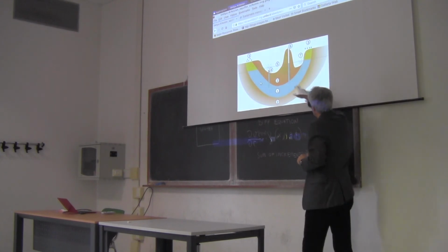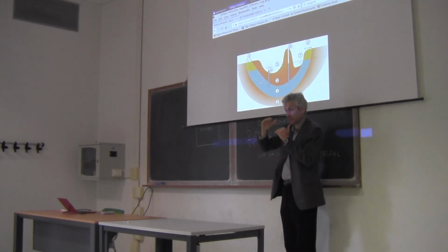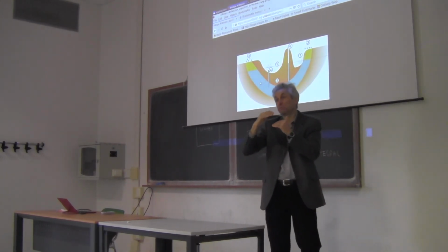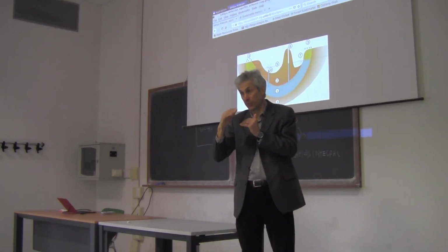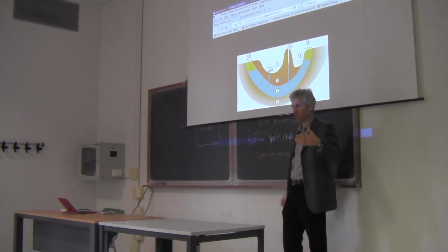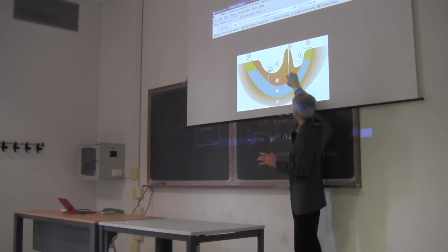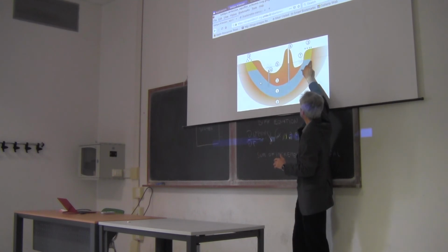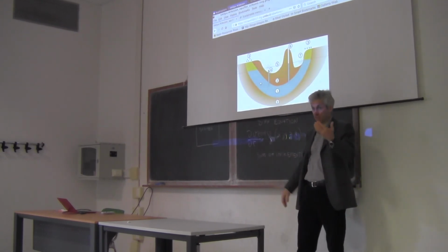And instead, when you have the upper part of the aquifer, like here, that is in direct contact through a porous media with the atmosphere, we call it a phreatic aquifer. Aquifer is a synonym for groundwater body. If you refer to this confined aquifer, but we look here, here it assumes the behavior of a phreatic aquifer, because it means that water is in contact with the atmosphere.